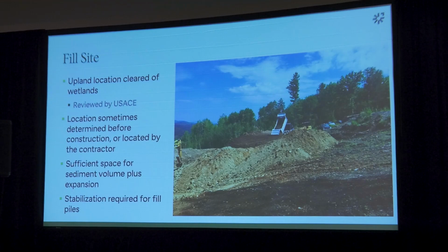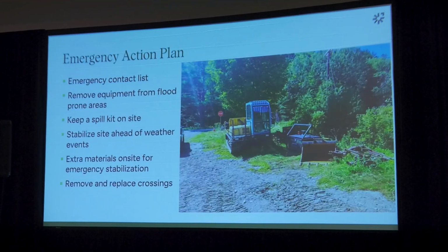Let's see, so emergency action planning, I think, is next. We have had some situations where the contractor really wasn't ready, despite our pushing here. But we really always want to make sure we have emergency contacts, people are watching the weather, not just us, the contractor making sure there's materials on site for stabilization if it's needed, and really buttoning up the site before any kind of storm event.